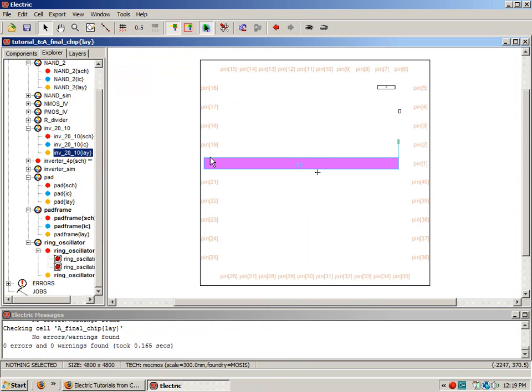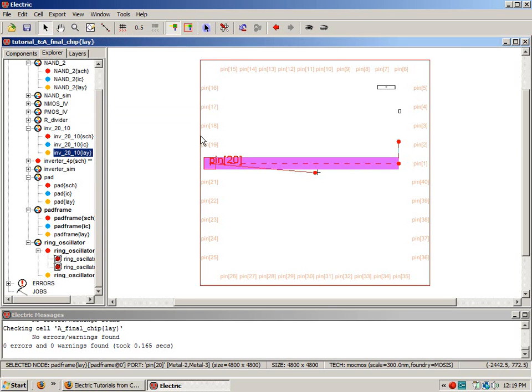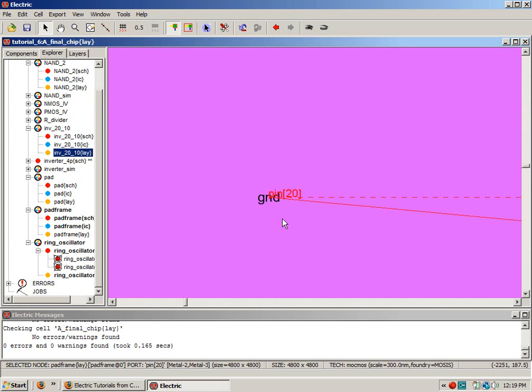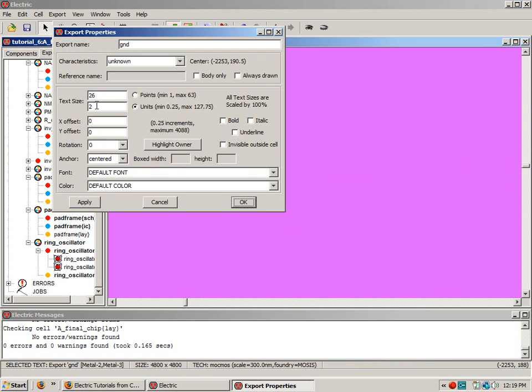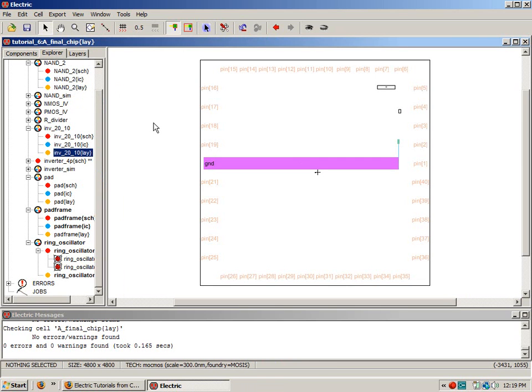So I'll go back, select special select, hit Control until I select the pin, do a Control-E, GND. It's going to be tiny, so I'm going to have to zoom in, turn the special select off, zoom in here, or I guess I could also just select everything and then go through and only query it or edit its properties and then remove the others just like I did with the pins. So let's set that to 125 just so I can see it. Then I've got to connect grounds up to the others, so why don't I do that right now before I go any further.